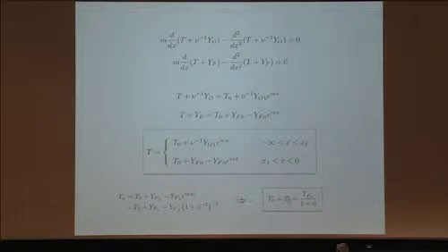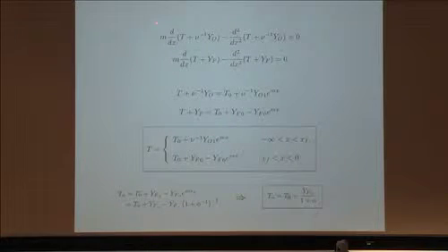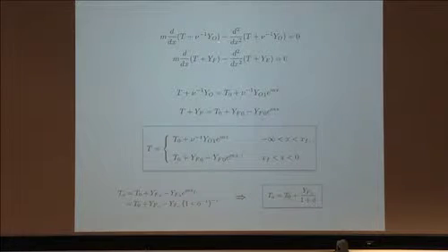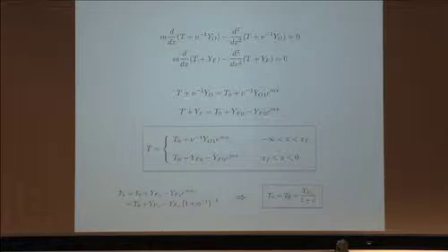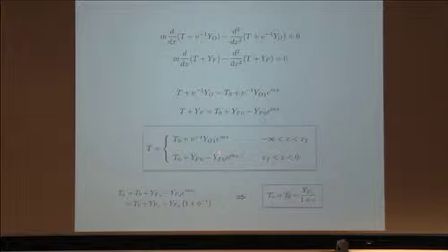Next, you can use the other two coupling functions, which involve the temperature. Okay. Remember that we can construct two other coupling functions. They are also conserved scalars when the Lewis number is 1. And if we solve for these two combinations, we get, again, two simple relations with the same exponential, e to the mx, right? Now, where YO is 0, that gives you the temperature. And where YF is 0, the second one gives you the temperature. So here is the temperature. So the temperature is given by those two expressions on the fuel side and on the oxidizer side.